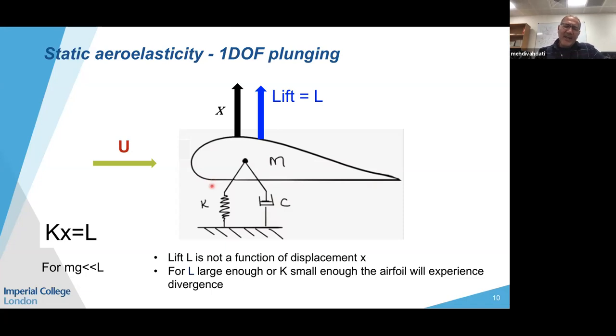You can see that by displacing the aerofoil, you are going to have some steady forcing in the spring. So even though there's no vibration, the steady loading of the blade has already created some forces in the spring. So that's one of the things which happens.